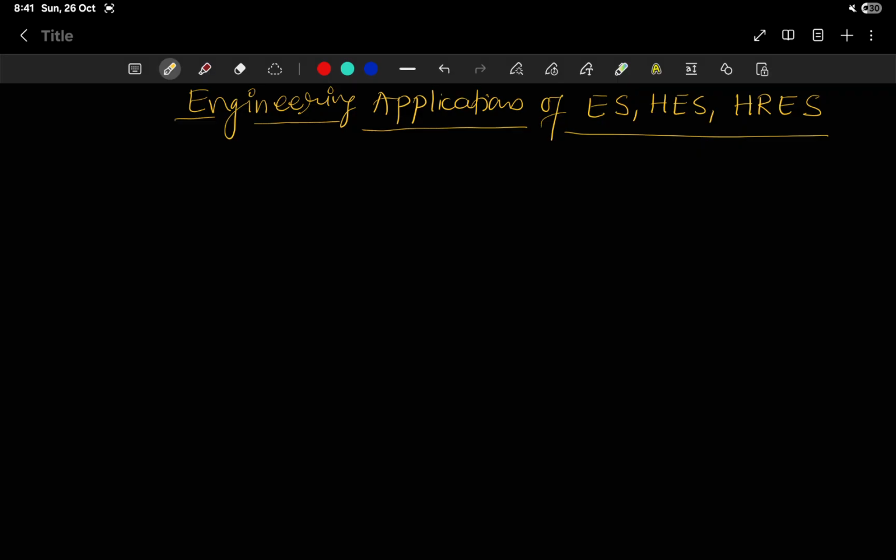We called it pearlite. In the hypoeutectoid region we got a region of alpha, that was proeutectoid ferrite, and a region of pearlite, that was the combination of ferrite and cementite. In hypereutectoid steel we obtained the proeutectoid cementite and the region of pearlite, that is alpha plus cementite, Fe3C.